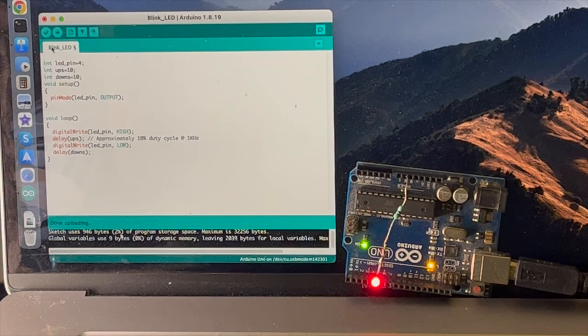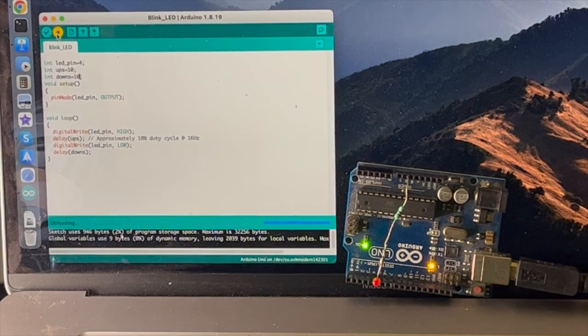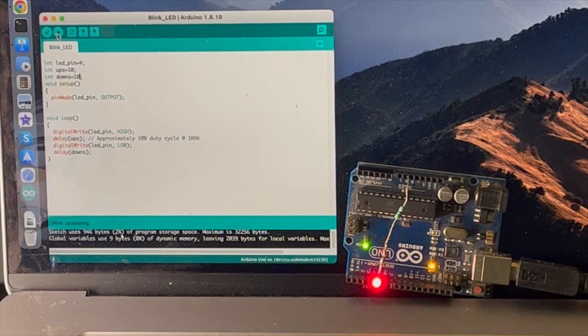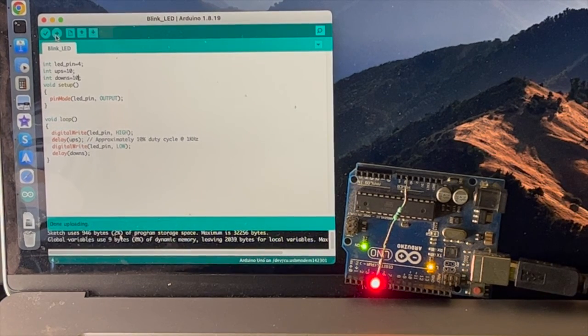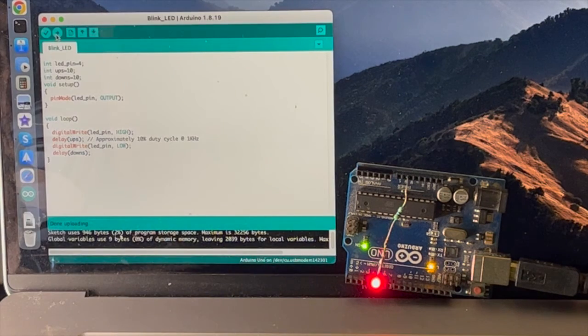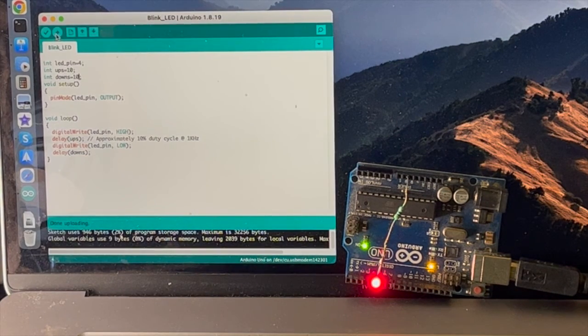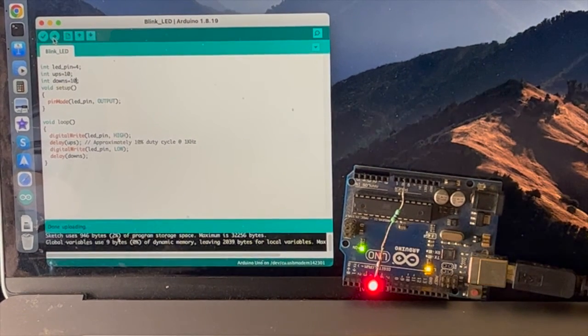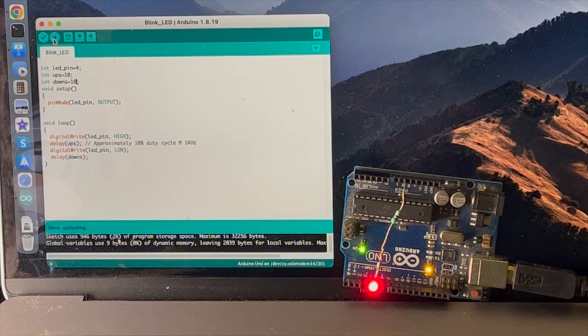We can flash it onto the board. Again, we can flash it as many times as we want to. Now you see that we are no longer able to distinguish each pulse because our eyes integrate the signal much slower than the pulse which is given. One of the advantages here is that once this program is flashed into the microcontroller, we don't need this computer. We can simply disconnect it from the computer and connect it to any USB power, and it would run in the same way.